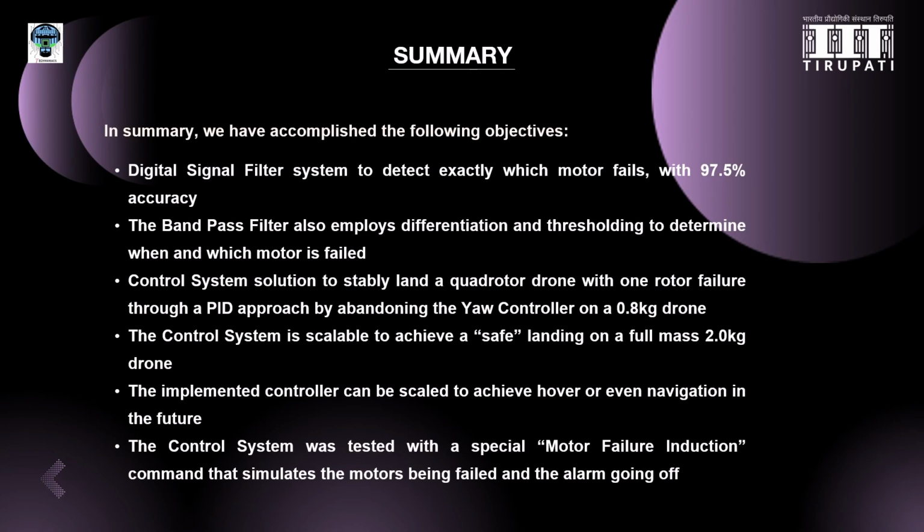It is worthwhile to note that the approach which we have adopted here is pretty scalable. The prototype we used for simulations was a lightweight test drone weighing around 0.7 kg. Since our approach is scalable, we believe the same control logic could handle a full-size 2 kg quadrotor, for example, a heavier delivery drone, as long as the motors have enough thrust margin. In other words, by adjusting thrust set points, the emergency landing controller can produce the extra lift needed for a larger vehicle. The PID gains might need tuning, but the architecture itself remains valid for the heavier drone.